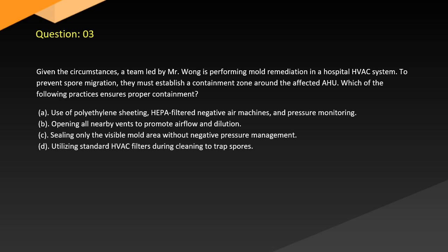A. Use of polyethylene sheeting, HEPA filter negative air machines, and pressure monitoring. B. Opening all nearby vents to promote airflow and dilution. C. Sealing only the visible mold area without negative pressure management. D. Utilizing standard HVAC filters during cleaning to trap spores.